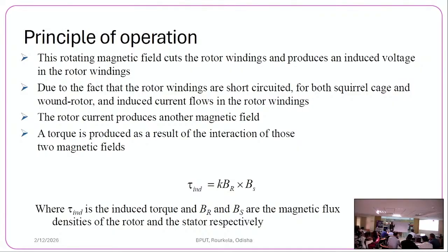And this current I2, when referred to the stator, is I2 dash or minus I2 dash, whatever you write. Then this core flux is produced by the magnetizing current Im, because a current is required to produce it. Then there is a loss component of the current, since some core loss will be there. So this is the no load current I0.